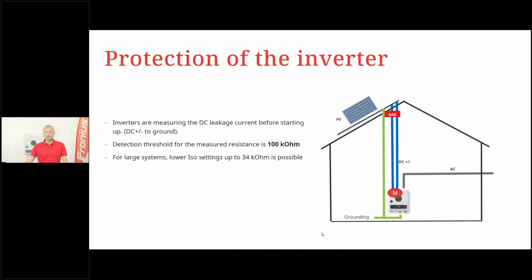Now, the protection of the inverter. The inverters measure the DC leakage current before starting up. Basically, this happens in the morning, and we check plus and minus to ground. If the resistance is below 100 kilo ohm, the inverter will not start and shows a state code. For large systems, the ISO resistance can also be adjusted in the web interface of the inverter and lowered to a minimum of 34 kilo ohm.